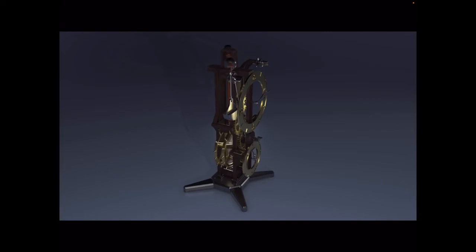The power of the clock is provided by a hanging weight. When the drive wheel is wound, it raises the weight to store potential energy. This energy is used to move the gears in the wheel chain. A rigid wheel allows the weight to be held while the rest of the gear chain is locked.